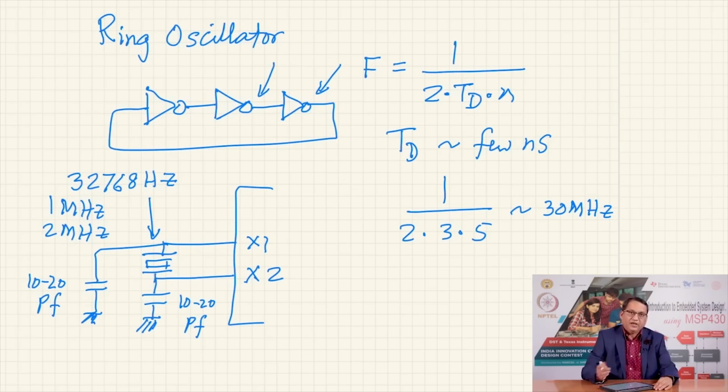The oscillator part, the active part of the oscillator, is inside the microcontroller. Therefore, all you need is a couple of external components, and this provides the source of clock. As I mentioned in the previous lecture, if the microcontroller offers clock scalability, then you should start with the lowest clock frequency crystal, because internally you could use a multiplier to increase the clock frequency to a high value that you would want at a given point of time.